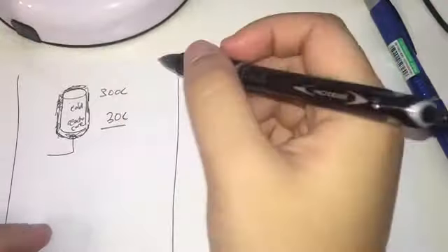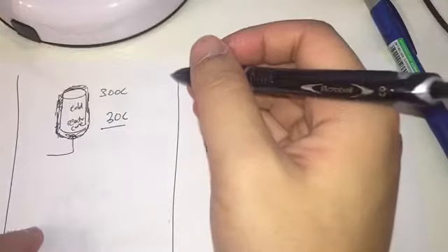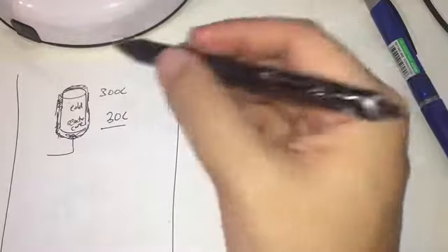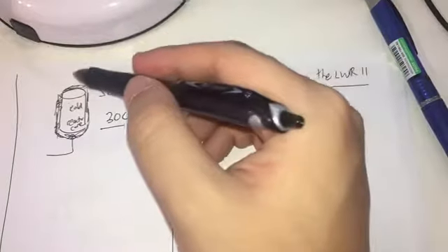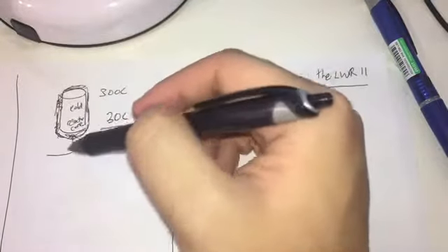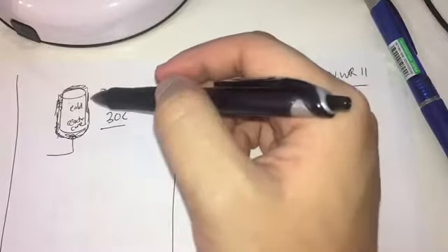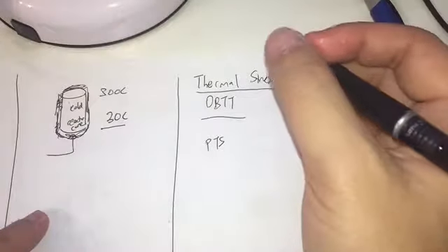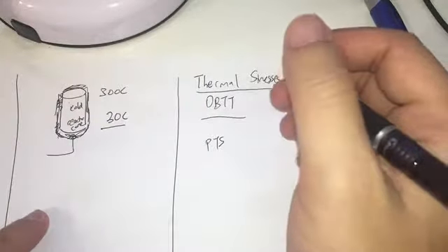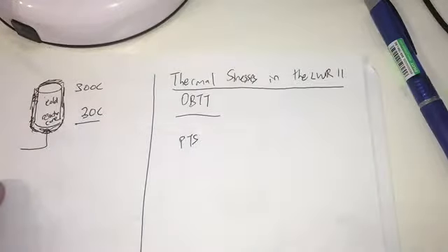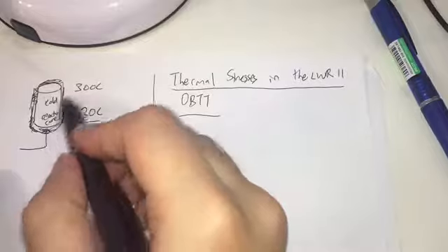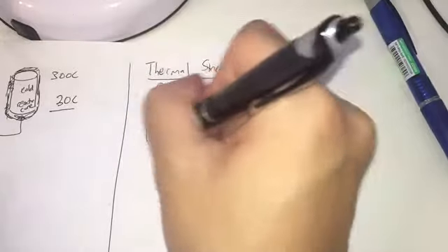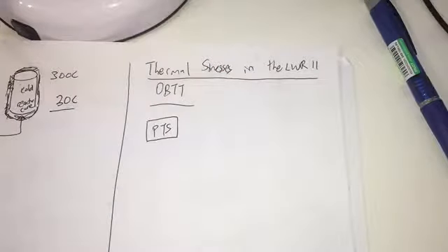Now, the reactor goes through PTS during an emergency core cooling shutdown kind of incident. During any emergency where the control rods are inserted into the reactor core, a certain amount of water needs to be pumped into the core to keep it cool because of the decay heat that must be removed, otherwise there is a meltdown. But doing so very suddenly can cause a huge temperature differential and some thermal stresses, and this is what is called PTS, or pressurized thermal shock.